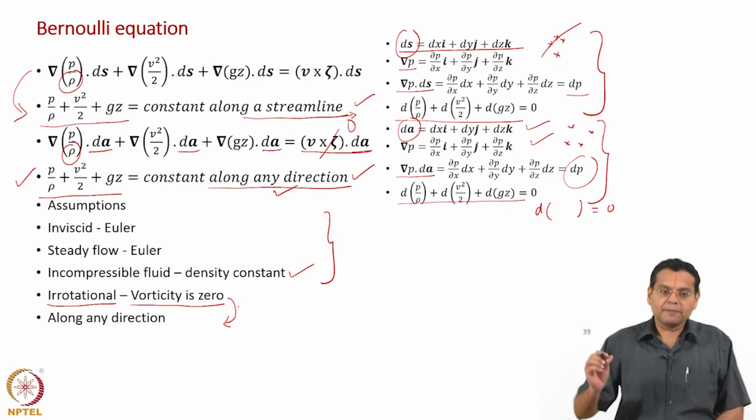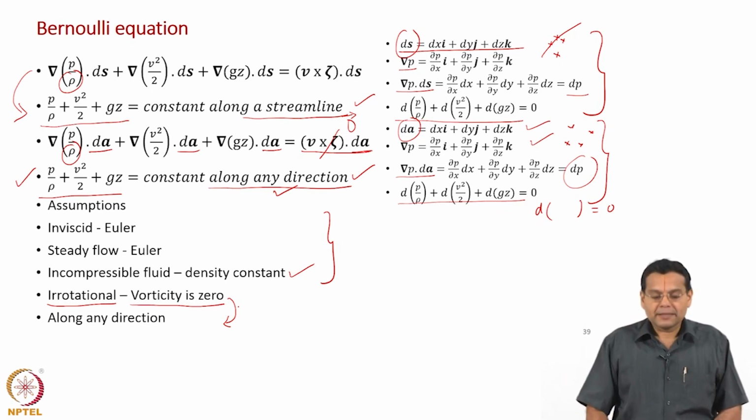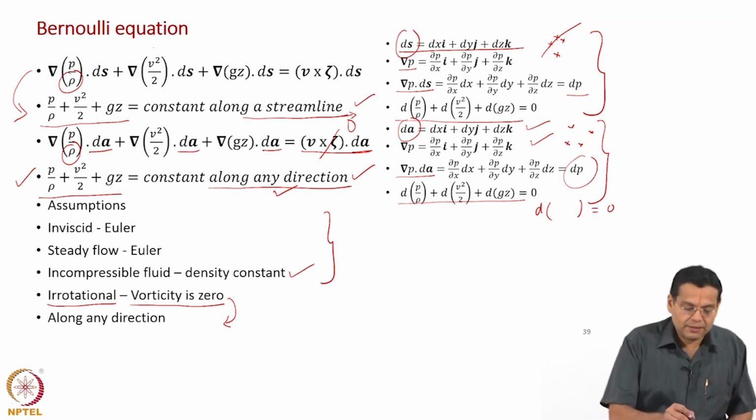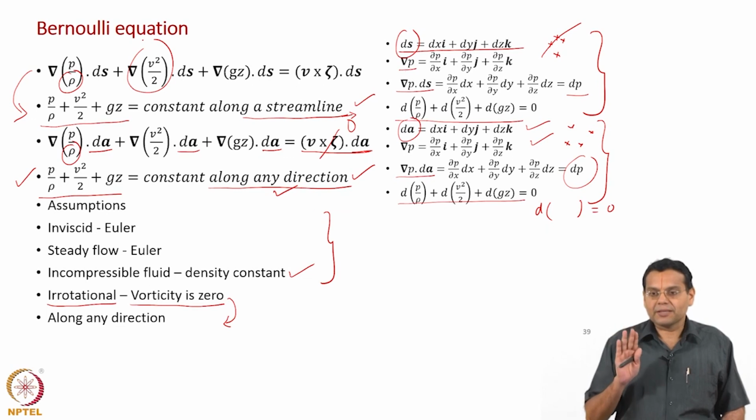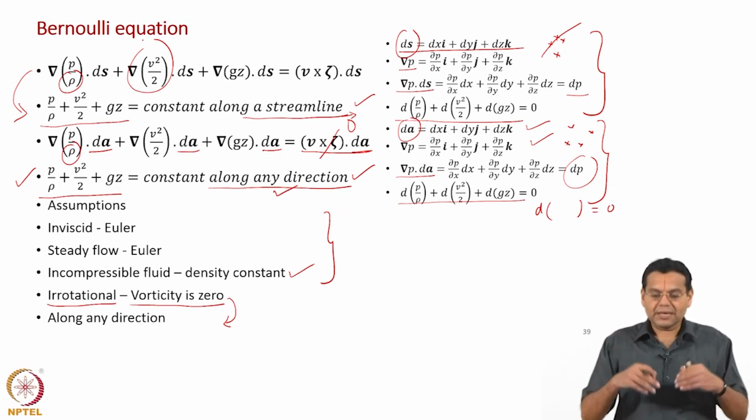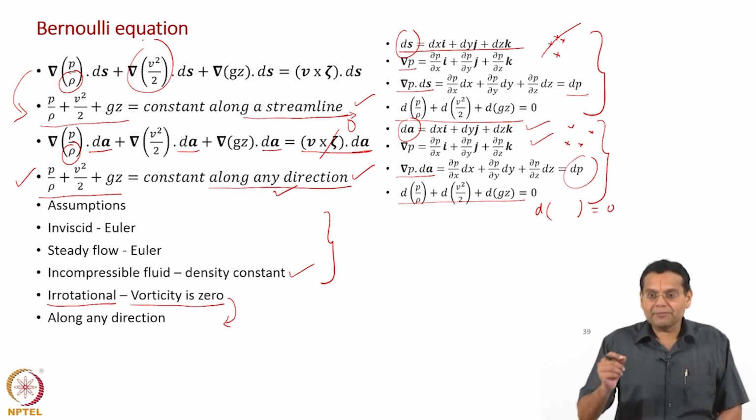They take a streamline, consider the movement of a particle along a streamline, they consider acceleration, which is this term, okay, and then for the forces they consider only pressure force and gravity force, that is all they consider, they do not consider viscous forces. That is what we have also done. Though we started with Navier-Stokes, we wrote down the Euler equation neglecting the viscous stresses. So, both have converged to the same physical significance, but the derivation is done in the beginning.